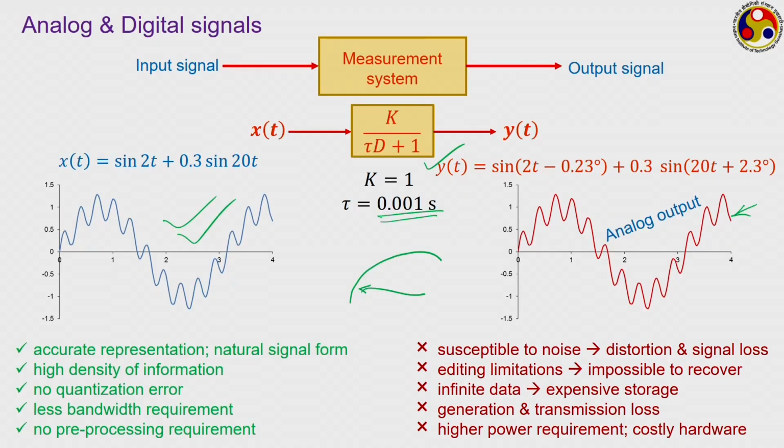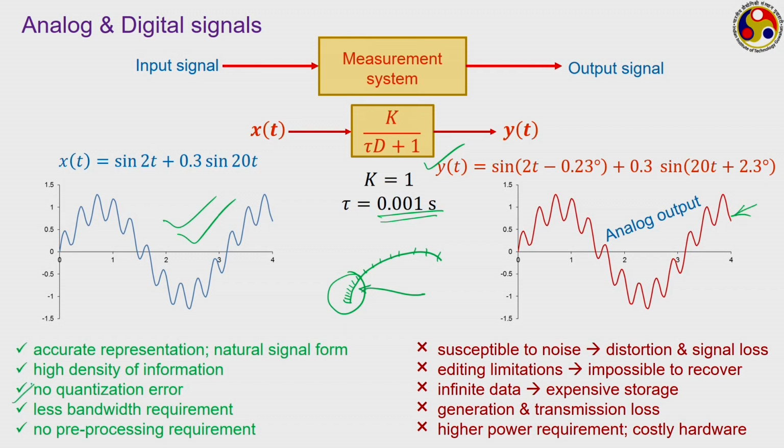And most often you will find that the scale on the device is not linear, rather the values are quite cramped up towards the initial part and then gradually getting relaxed as we move towards much higher values. So linearity is not maintained, and reading values with a high precision within this zone can be very difficult.